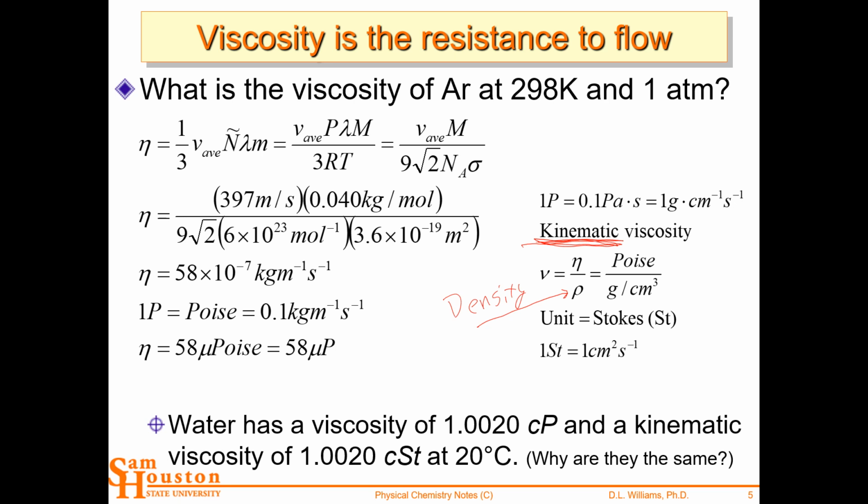The molecules that are trying to move are imparting a force onto the surface, and so you can actually get the surface to feel a force by flowing something through a pipe or across a surface. In fact, that's how they actually measure viscosity, is the drag it puts on the surface. So if you look at a rheometer, which is rheology, the science of flowing fluids, they'll have plates and cones and cups. So you have a motor that drives this cone. Let me just draw it.